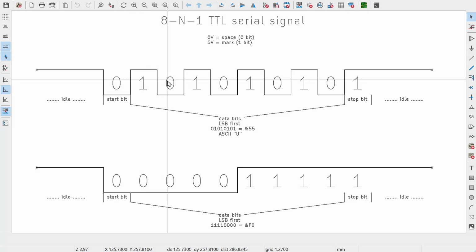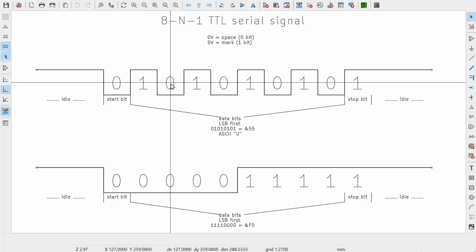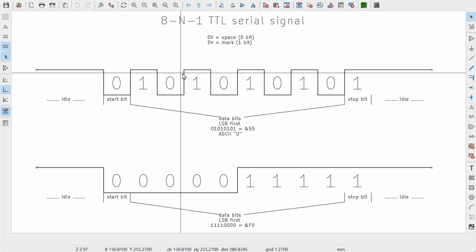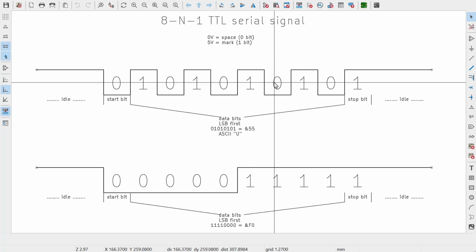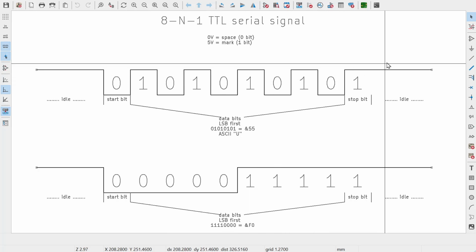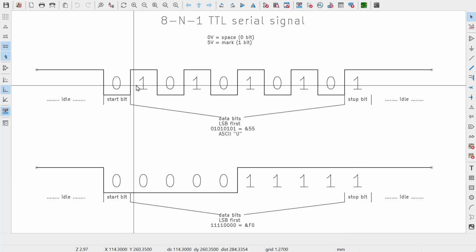After that, we need to wait an entire bit period before the next bit is sampled, so that will be 35 ticks from that point on, so we'll have to reset the counter to 34 at that point so it counts down correctly to the point we want to sample over here. And from that point on it's just going to be counting down from 34 through 0 every time we go to the next bit.